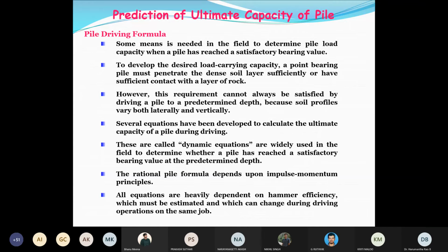So that means, when you apply repeated impacts on the pile, anything can happen. The pile can get broken, or only the top may get damaged while the bottom portion remains the same, or cracks may form, or the top of the pile may get fissured. Anything can happen. We also do not know whether the alignment of the pile is perfectly vertical or not.